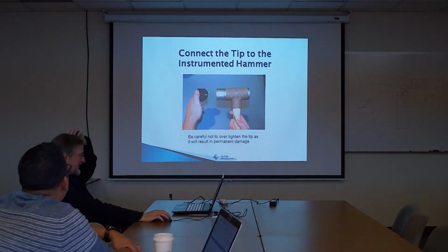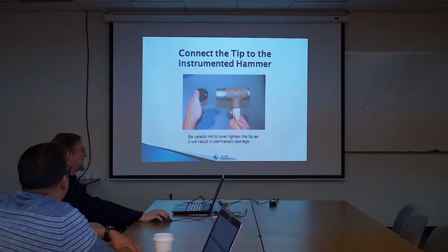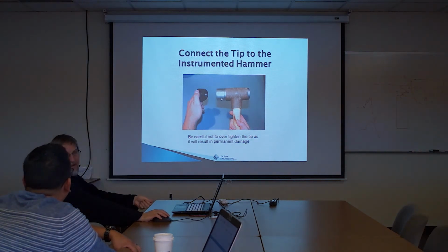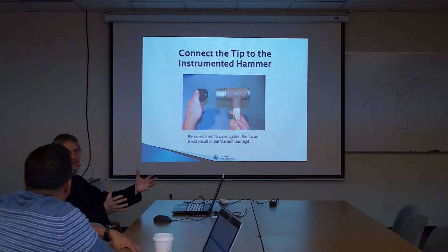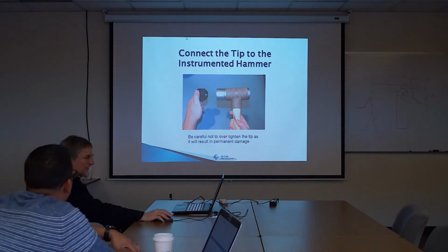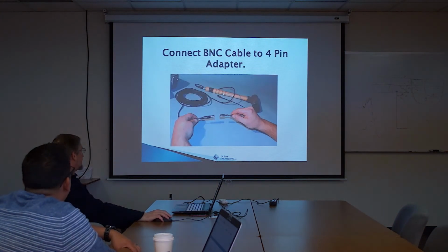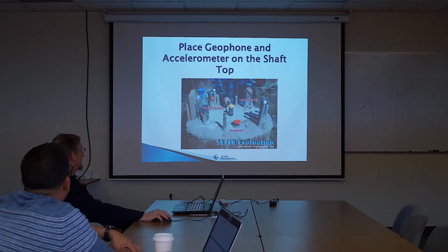And you don't worry about this. This is for the IR testing, it uses a $1,400 hammer instead of the cheap hammer. It has a load cell built in that measures the strength of your impact, and the waveform. So it gives a waveform from the impact that we can then divide by the output to come up with the impulse response. So it's an input divided by output kind of thing. We're not too worried about that. This is pretty straightforward, accelerometer, you connect it up.